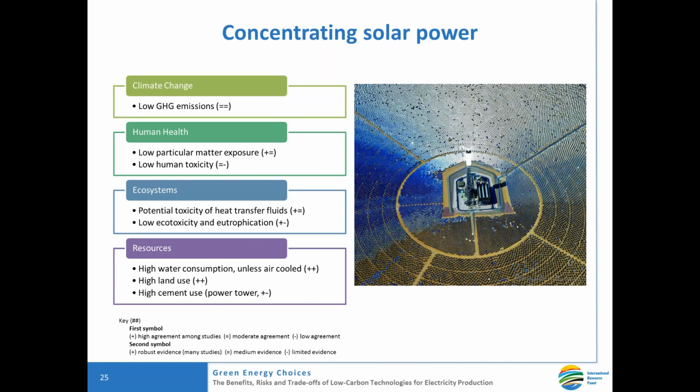There is resource use associated with this technology, and that is actually a problem here, and that is the water use. As this technology employs direct sunlight, it works best in areas that have low humidity. However, areas that have a low humidity also generally have little water available. And the water here is used to cool the steam engine.